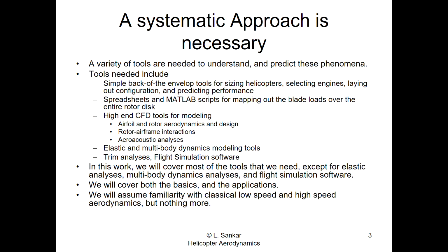And then you'll pass the aerodynamic loads to a structural dynamic solver, aeroelastic solver. When the blade bends and deforms, then you'll put it back into your CFD. Then the trim of the vehicle, that means the thrust it produces, the propulsive force it produces, has changed. So you may need to pitch the blade up or down to increase the lift, to change the propulsive force. Then you'll trim the vehicle using flight dynamics software. So everything will be coupled.